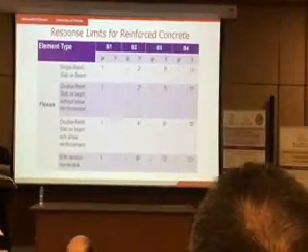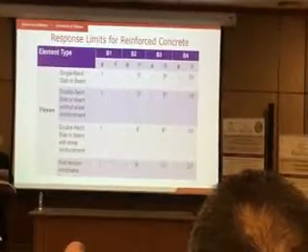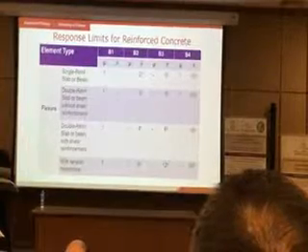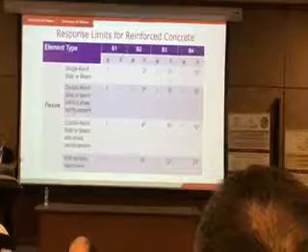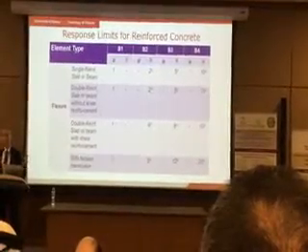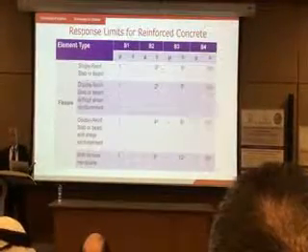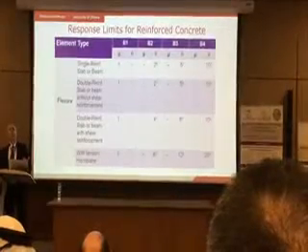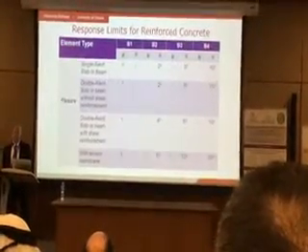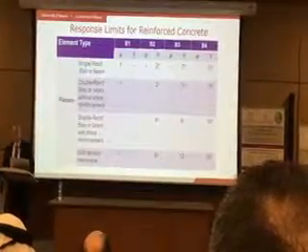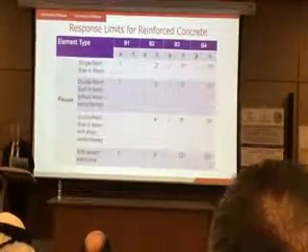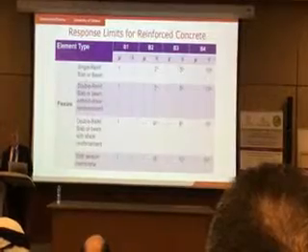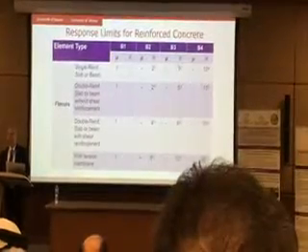But in blast, because they look at glass windows, they look at doors, they're not structural. The whole profession evolved from security people, not from structural engineering people, and that's why they started using support rotations. Support rotations are used under high displacements, so it's either ductility or support rotation that is specified in the CSA standard.